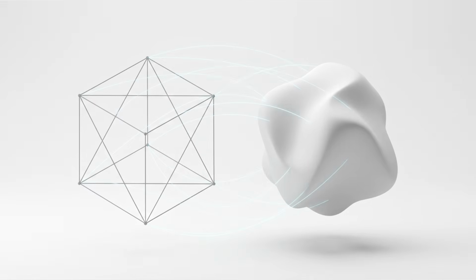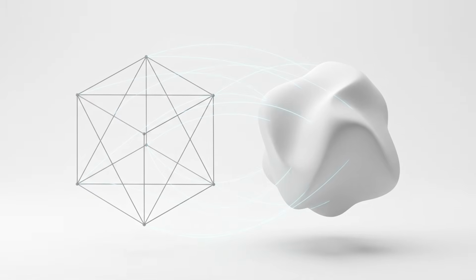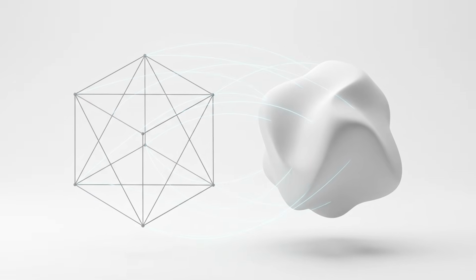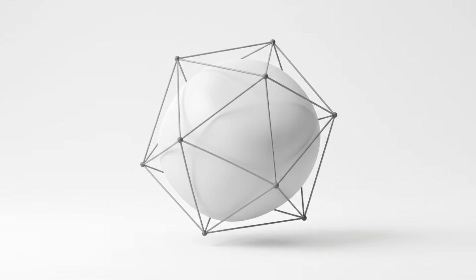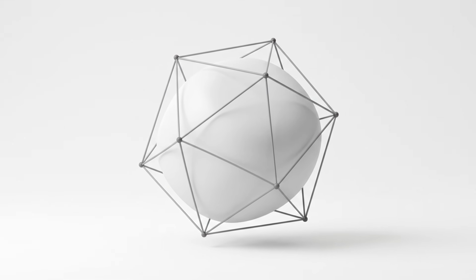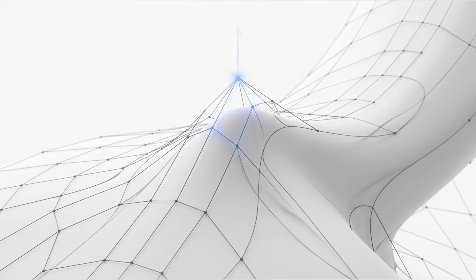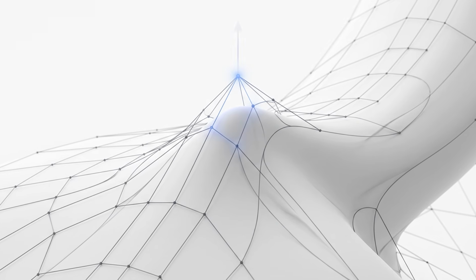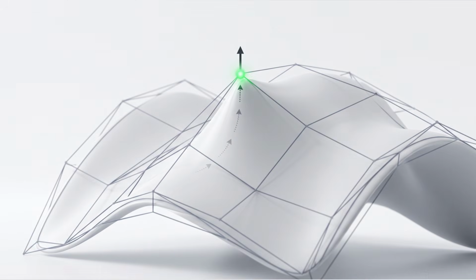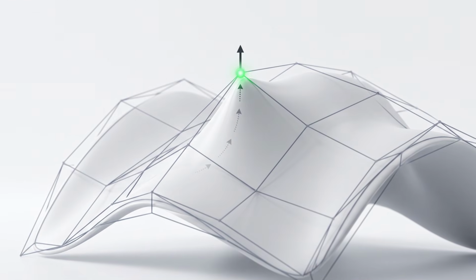Instead, we modify a control cage, and Rhino calculates the smooth final surface based on that structure. This process is done through a method called subdivision. In this method, the model's mesh is divided into smaller sections while becoming smoother at the same time. Rhino uses the Catmull-Clark algorithm for this process, which is widely used in product design, animation, and game development.